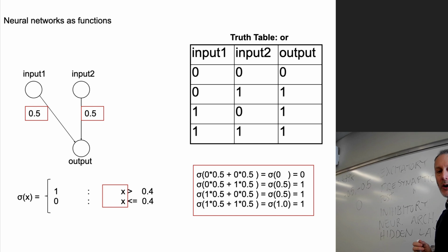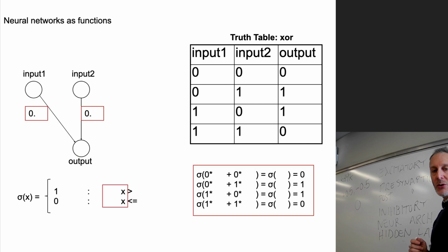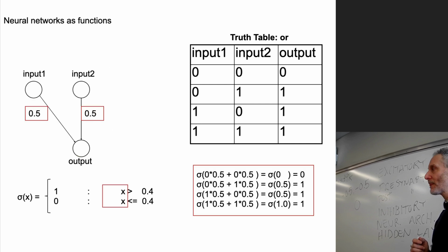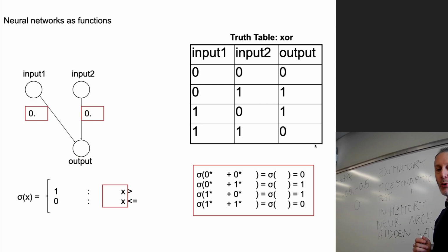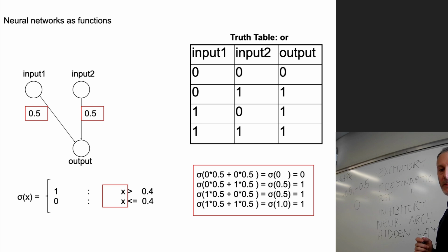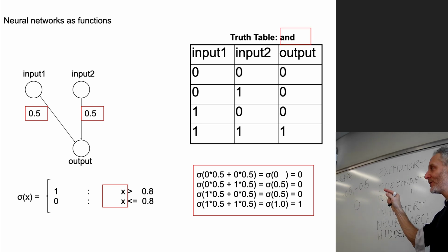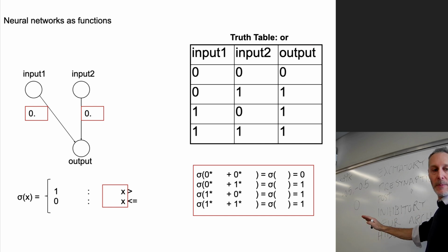Have a look at the OR. Look at the outputs of the OR. OR shares 3 output values with exclusive OR, and only in the 4th case is it different. So we want AND, which we know fires only in the 4th case. We want, when that AND lights up, for it to take away or inhibit OR. We want it to suppress OR.